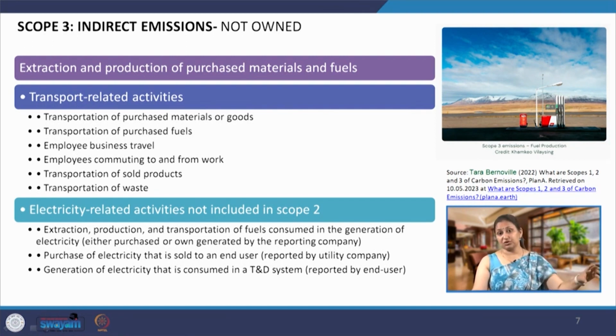Now, compare the emissions associated with the CSEB with an autoclaved aerated concrete block, the AAC block. The AAC block is completely made out of cement. So, if we compare the emissions of these two blocks, none of this is going to be manufactured on my site. They might give me similar thermal performance, so that my operational energy is the same, but the embodied energy associated with these two different products will give me the scope 3 emissions that my company will also be declaring.